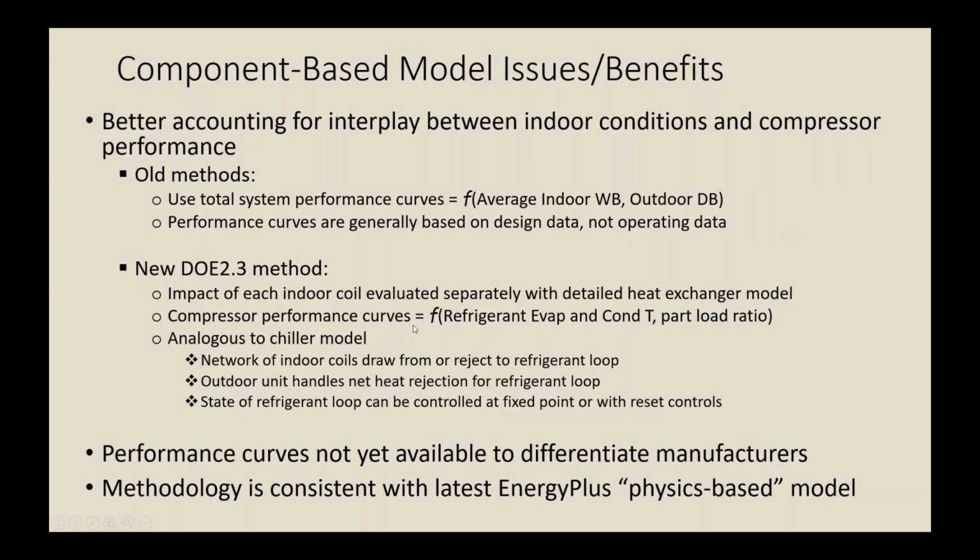So this component-based model is a little different from the way simulation engines have handled VRF in the past. In the old methods, the performance curves that you'll find published out in the field generally are given as a function of an average indoor wet bulb temperature and outdoor dry bulb temperature.